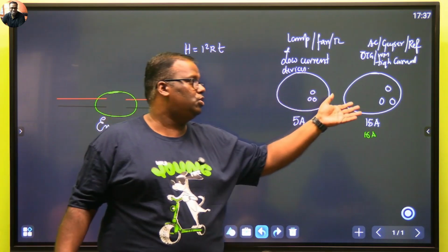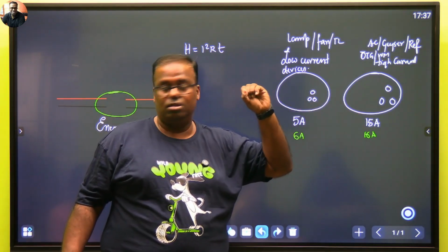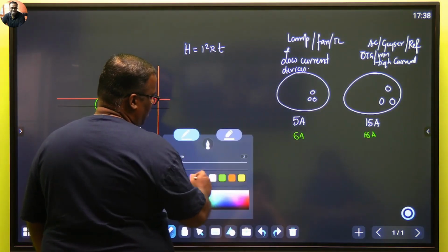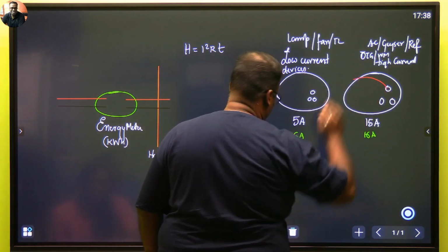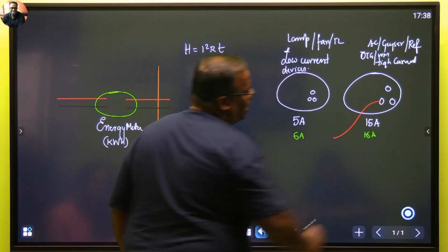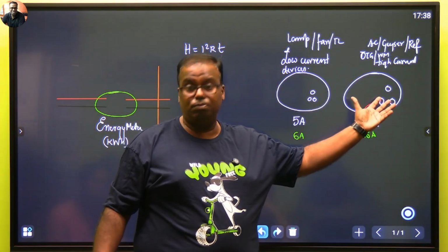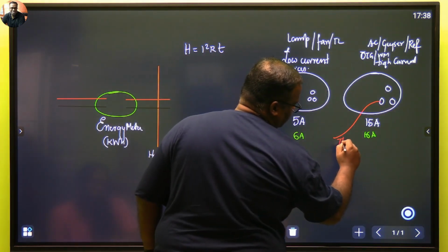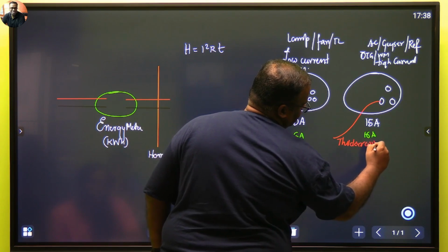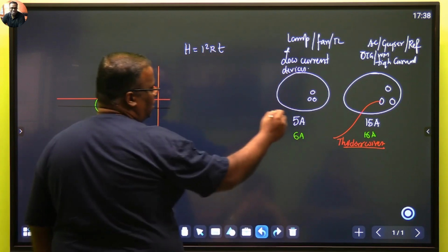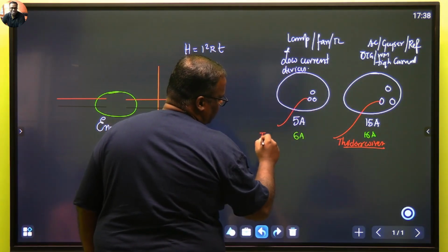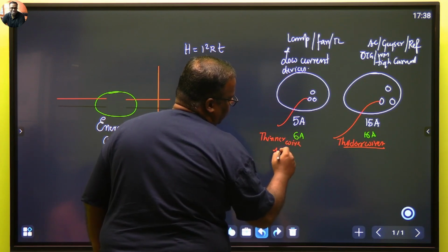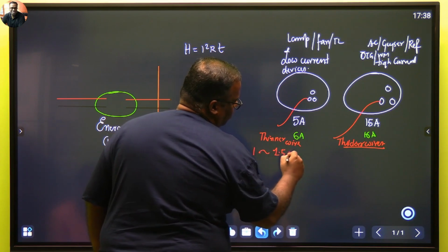So what should you do? You should actually try to work on thicker cables. The cables that we will be using for this particular wiring, and like this, there may be many sockets in my house. In kitchen, there may be 5, bedroom at least 2, living room 1. So all these will be with thicker wires. And this one will be done with comparatively thinner wire. So these we usually do something like 1 or, just for your knowledge, 1 or 1.5 square mm.